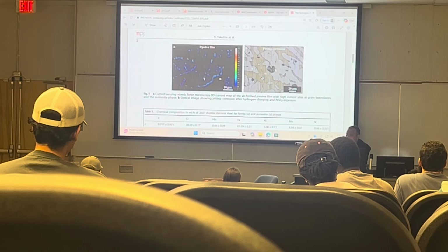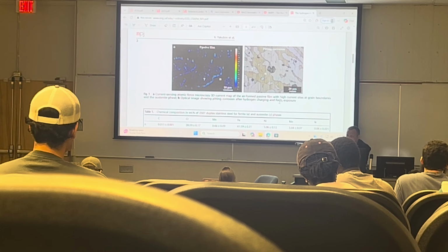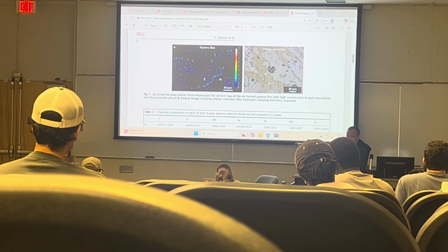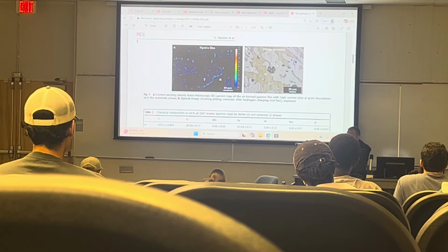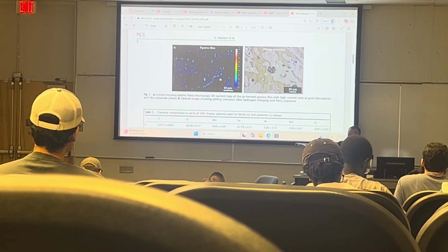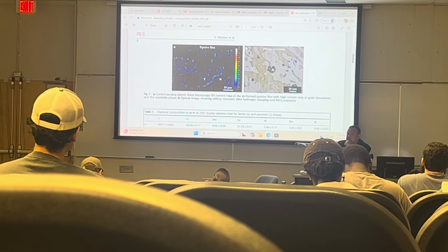And what people have noticed is that in the corrosive environment, in iron chloride solution, the pitting always starts in the gamma phase. And there was no explanation why this was happening the way it was happening.